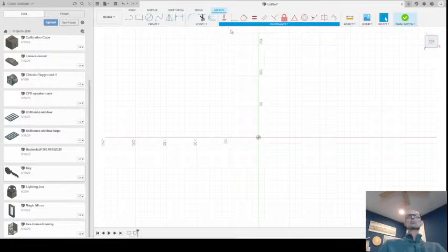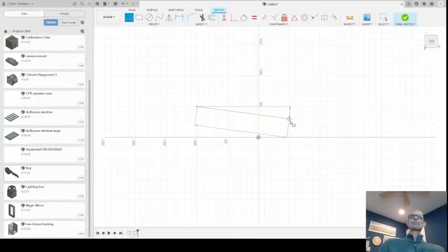So horizontal/vertical constraints a line or 2 points to lie on either the vertical or horizontal axis, whichever is closer to the current alignment, so it snaps to that. The instance here is I can create a line, so I'm in sketch mode and I click the line tool, which lets me define a beginning and end for my line. I'll click here and extend out, and notice I'm maintaining the angle so it doesn't deviate from that horizontal line. Then I'll click another time, and that sets my line.